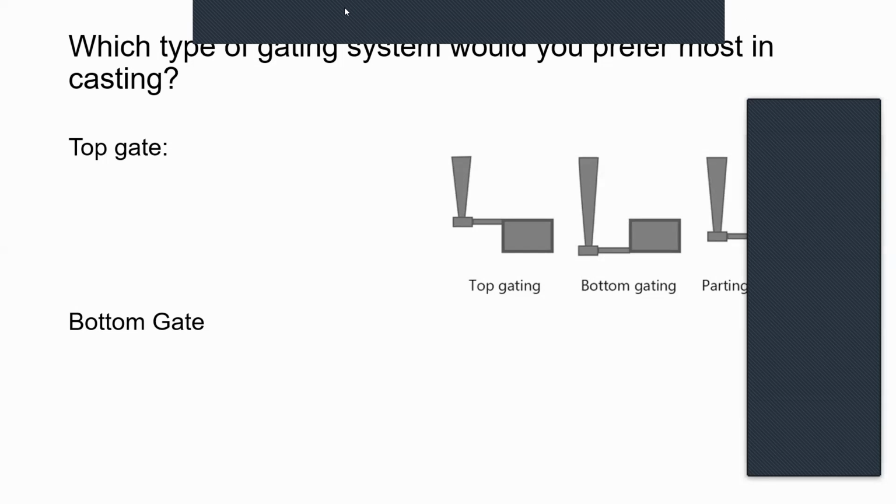So horizontal gating? There is nothing called horizontal gating actually. Actually, I'd seen it in a book. No, this is not that. This is called bottom gating. How can horizontal gating happen? Can you make a particular liquid flow just at level surface? You can't, right?